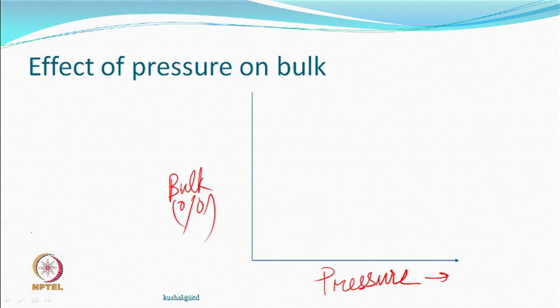But in this case also the bulk increases. The increase in the bulk is not to the same extent as you saw with the increase in overfeed. So much yarn is available to do that. Here the length of the yarn available is constant.